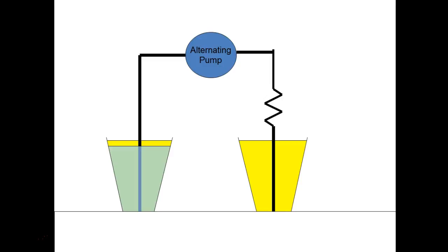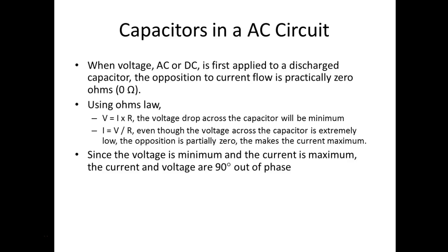If you've got a capacitor that's real hot, what does that probably mean? It's bad. That means current flows through it and something's happened to it. Normally they're sealed up real good, especially the electrolytic capacitors, and they'll actually bulge out on one side and they will blow up too, by the way. I'll show you the video of them blowing up capacitors on purpose.